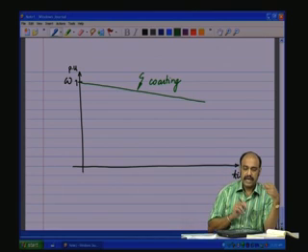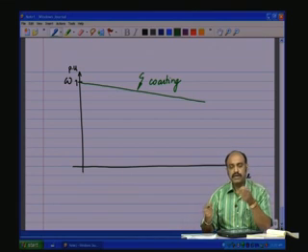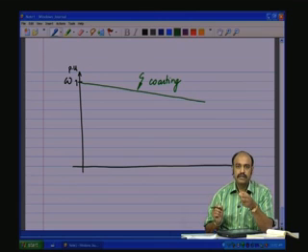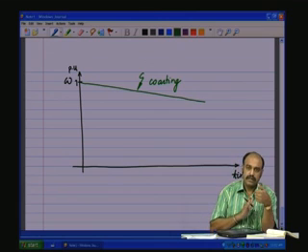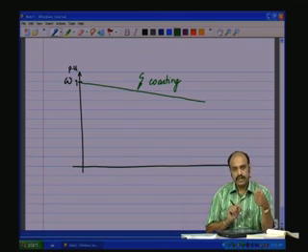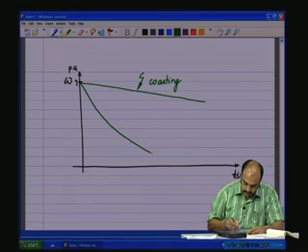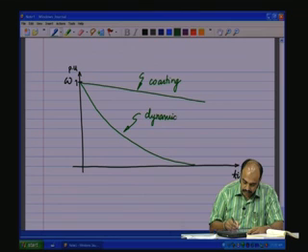Now, in the case of dynamic braking, instead of applying the lossy element on the mechanical side, we are applying the lossy element on the electrical side by putting a resistor, and the braking effect can be something like that with a time constant. So, this would be dynamic braking or mechanical braking.